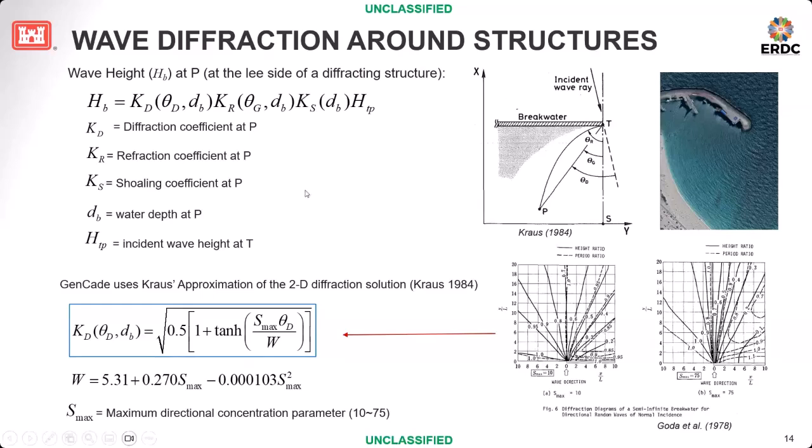In fact, we have implemented an analytical solution of diffraction around the semi-infinite breakwater. Those changes can be approximated by this equation developed by Nick Kraus in the early 1980s. And personally, for the purpose of long-term simulation, this estimation of the diffraction coefficient is pretty good. It's good enough.